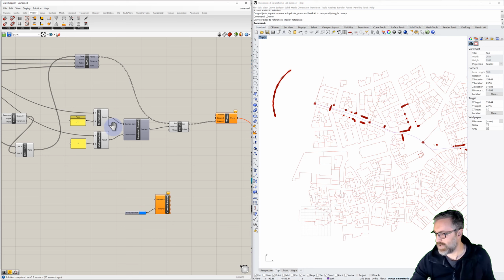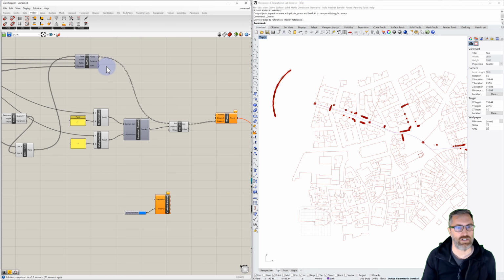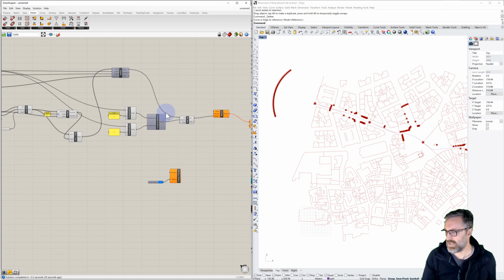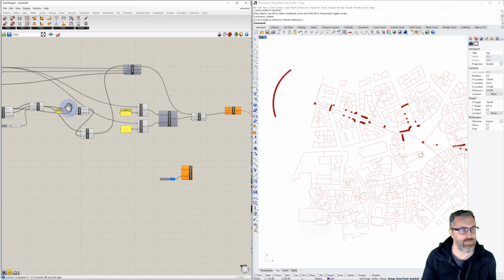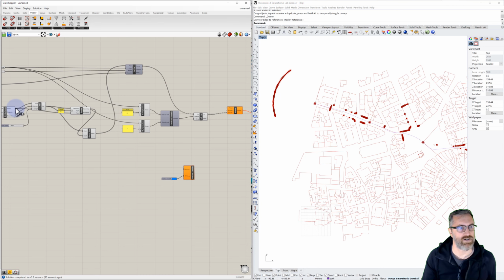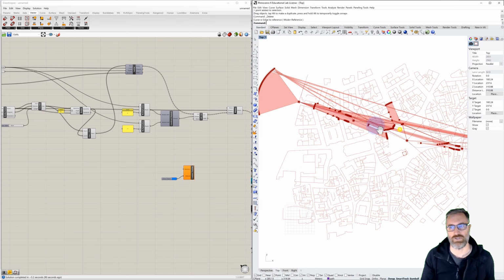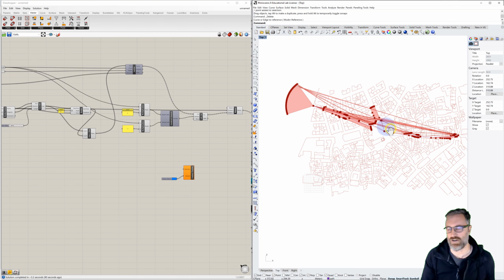And let's see where we're at with this. All of that seems to be working. What we don't have is our stream isn't working. So we've plugged in our sublist. What do we need? We need our points that come all the way from our divide curve. So I'm going to go back to the divide curve, pull this all the way over and plug this into the weave. So now we can see we started to get closed boundaries, but it's a little bit crazy.